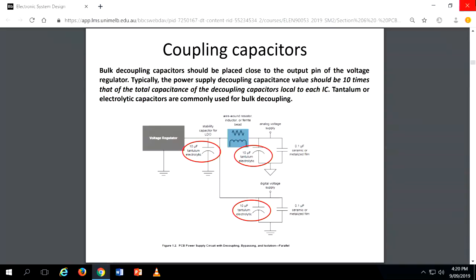The bypass is 0.1 microfarad, small, right? Because we don't have much space, so we will be connecting only the required values. So when you have switching, what will happen is that all the noises will be shorted through this one.